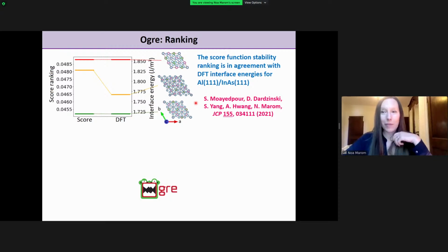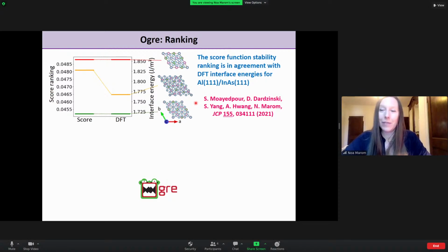Absolutely. We do see convergence issues with some of these large interface calculations with VASP. We do use VASP. My students work very hard to try to figure out how to converge these calculations. And we did put in our papers the parameters, the flags we used in VASP in order to get them to converge. And it's especially tricky when you have magnetic materials.